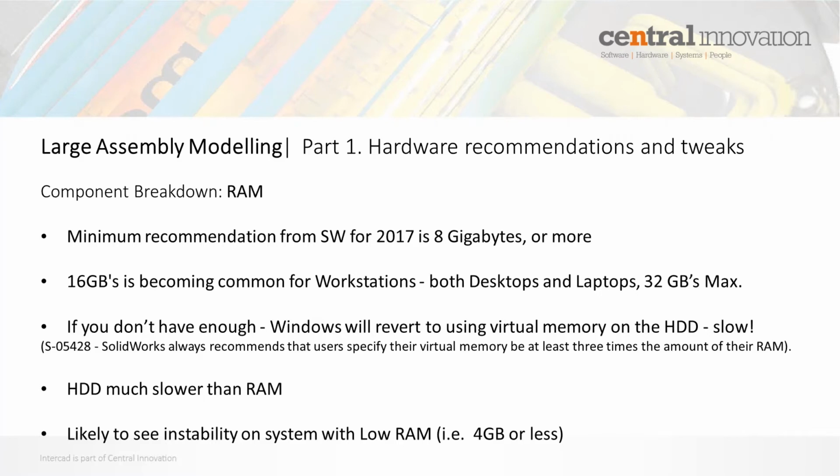My discussions with SolidWorks technical support would seem that moving much beyond 32 gigabytes at this time is probably slightly overkill. So that's probably where I would say that the maximum level is at this stage for desktops and laptops. But 16 gigabytes is probably most common. But certainly SolidWorks will use as much memory as it can get its hands on, so if you're willing to fork out the extra expense for 32 gigs, then all well and good.